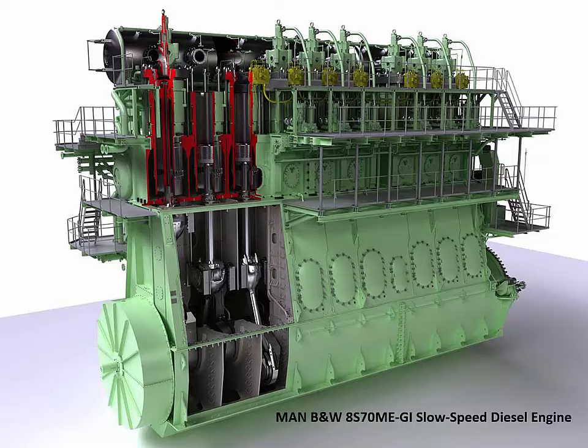When you're maneuvering, for a direct reversing engine it is a requirement that the bottles store enough air for at least 12 consecutive starts. For a non-reversing engine, it is at least 6 consecutive starts.